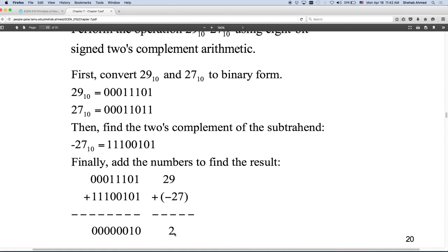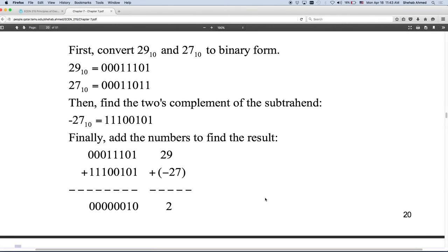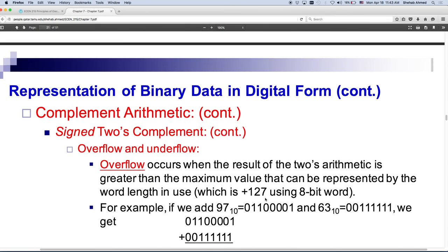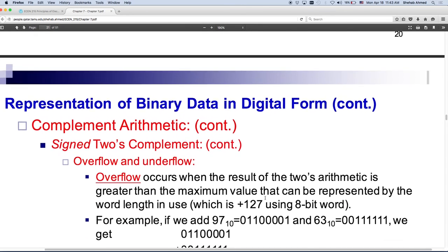So we were able to do a subtraction by converting a number to binary, taking its 1's complement, adding 1 to convert it to 2's complement, and performing the binary addition. So you see the value of the material we introduced at the beginning, just to reach this subtraction. We're not going to try to do multiplication and division. We will just do addition and subtraction, and that's it. We'll stop here, and next time we'll continue.